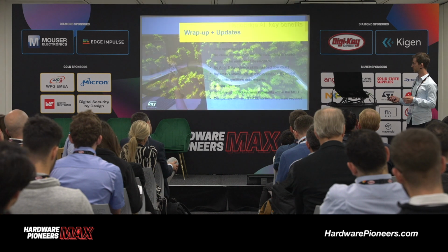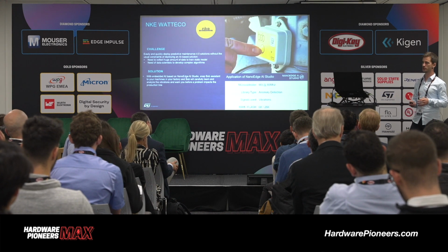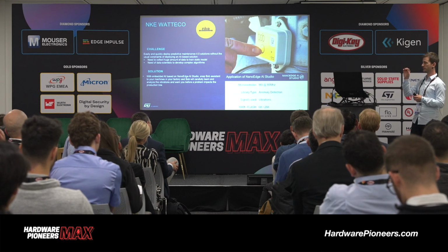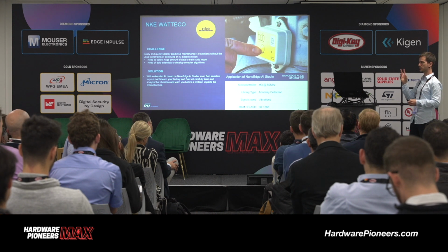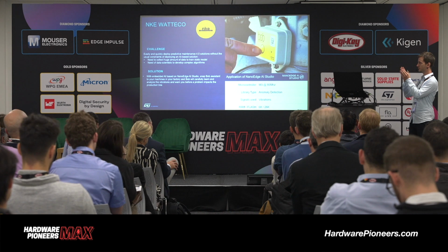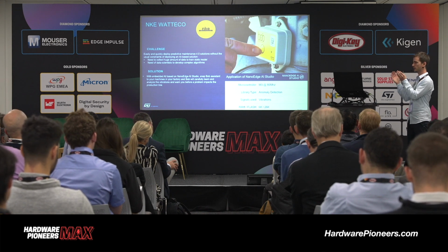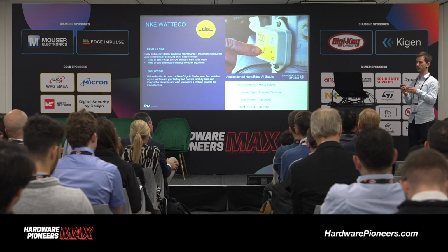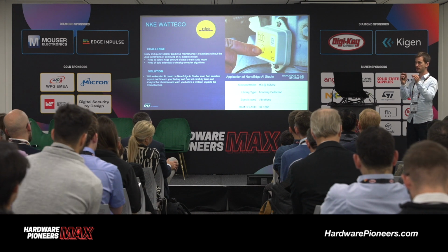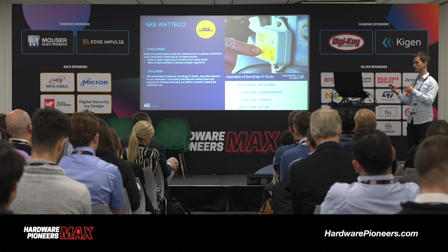For example, if I go back to this Bob Assistant, one of the first devices developed, it was not doing continuous monitoring for weeks, right? It slept most of the time and then woke up every 10 minutes to do one little iteration of inference. If it sees a nominal state, it goes back to sleep for the next 10 minutes. Otherwise, if it sees something weird, for the next minute it will do many more inferences, like every 10 seconds or so, to confirm whether there's a real anomaly or not. If there is, it blinks an LED or sends a message to a remote dashboard or whatever, and then goes back to sleep. So indeed, you can do it with the AI itself, or by just being a bit clever in the final code and spending as much time as possible sleeping, which is probably the preferred way to do it, and which you can pretty much always do.